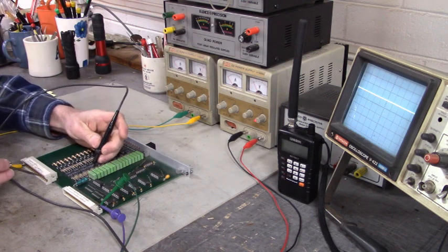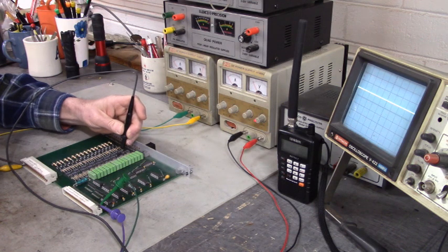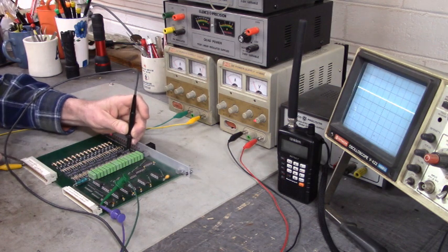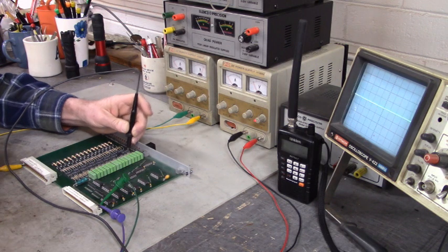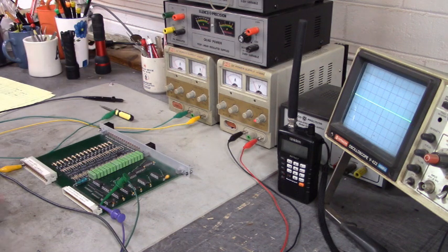It's amazing that you are able to test these circuits outside the machine. This is probably how they do it at the factory when they manufacture these cards. They got some poor soul like me out there with the probe to ground on the 24 volt DC side and oscilloscope, looking at the output of the opto-coupler. Oh, there you go.